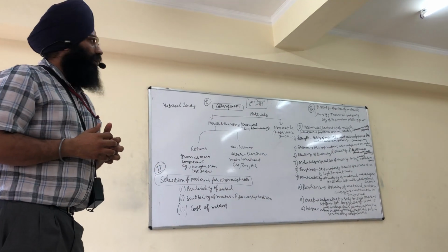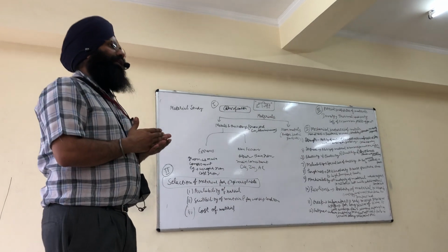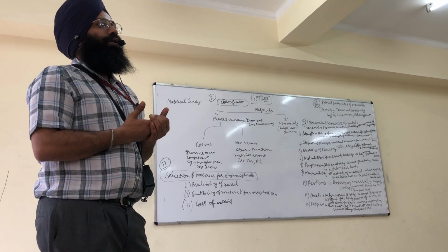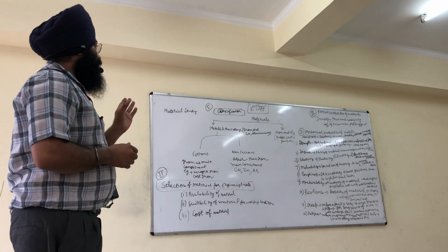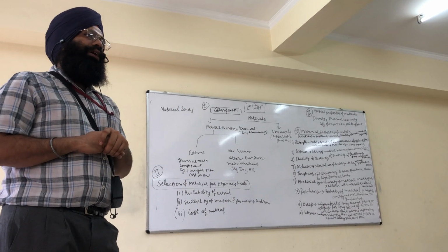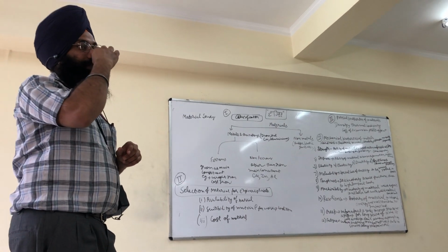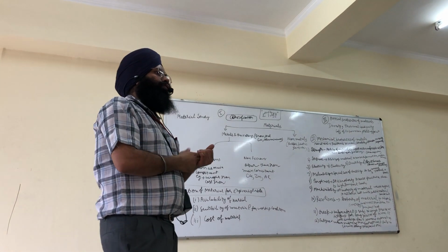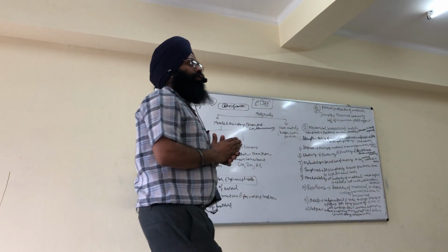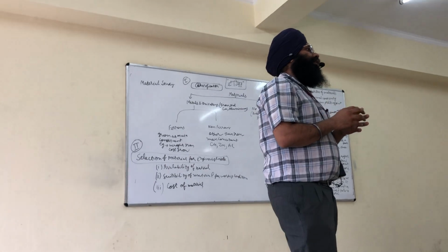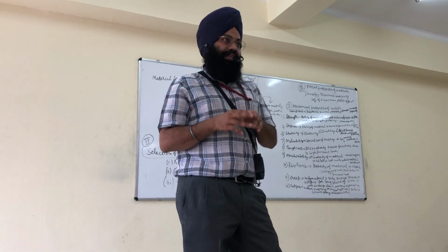Materials are basically classified into two parts: metals and their alloys, and non-metals. In metals and their alloys we have iron, steel, copper, aluminium. In non-metals, you know that we have rubber, plastic, cork, glass. Further, metals are classified into two categories, ferrous and non-ferrous. In the ferrous part, if the material has iron as the main constituent, then we consider that under the category of ferrous metals.